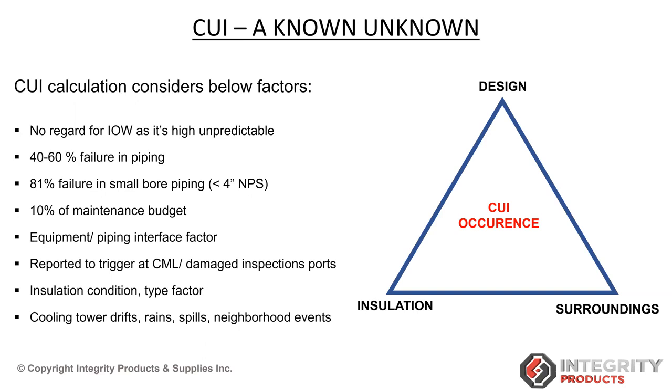And the reason we are talking about CUI in the context of this presentation is that there are many instances, from the location of the damaged inspection port or the location of the bad CMLs, where there is likely moisture intrusion. And we will talk about that in upcoming slides, and how the API standards talk about that.